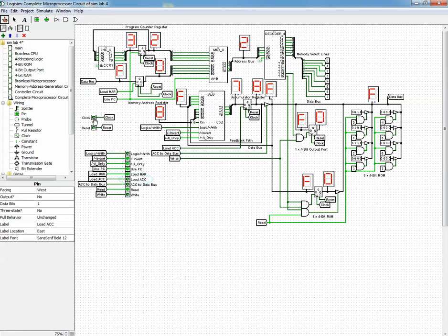And then when we tick the clock, the F is passed to the input of the multiplexer. Right now I can toggle this input, which is use PC, use program counter. I do not want to use program counter anymore, and this is why the F has passed to the decoder, and pin number 15 is being activated.